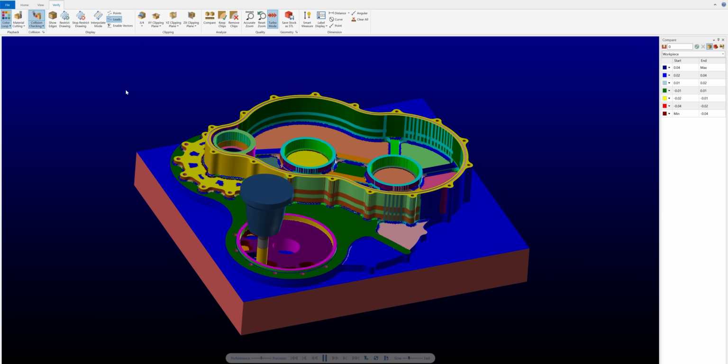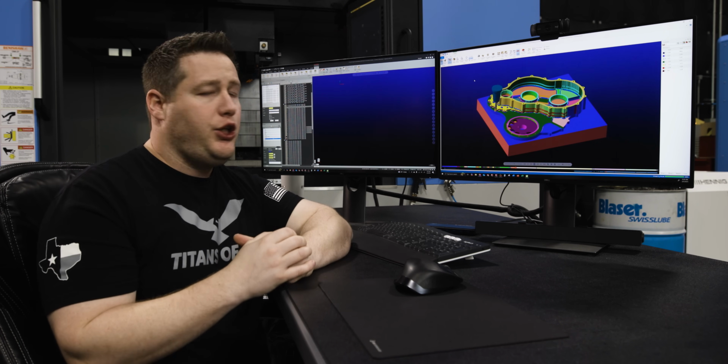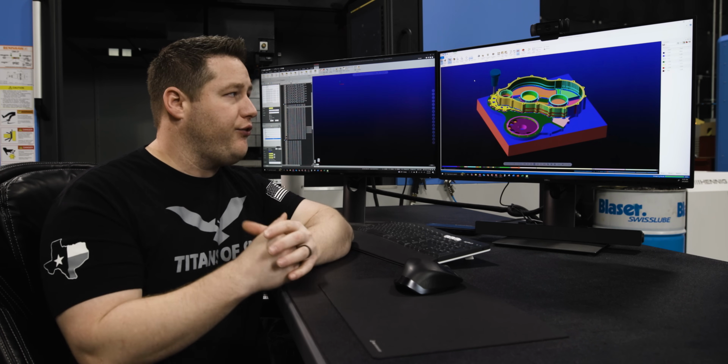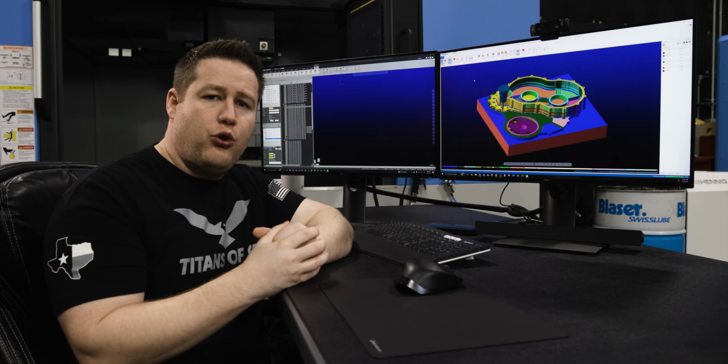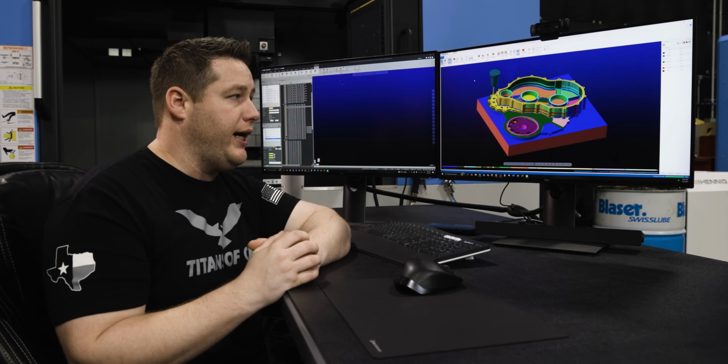Now, one thing that might be beneficial, because it does take some time to build that out, right? Especially to add your cutting parameters that you use. So one thing that you could actually do to get going faster is maybe use the Cam Assist tool library that they give you, because it has so many tools, to get a more complete program, and then go in and just switch the tools out with the tools that you use and the cutting parameters that you like.